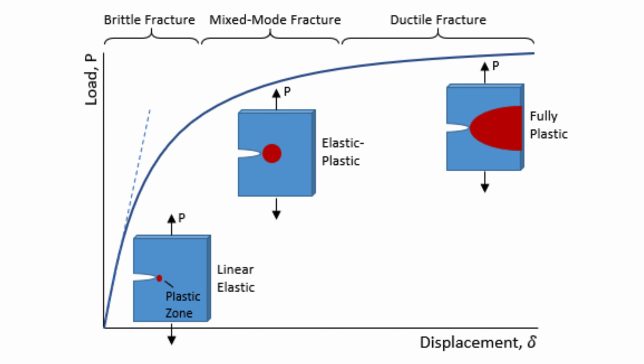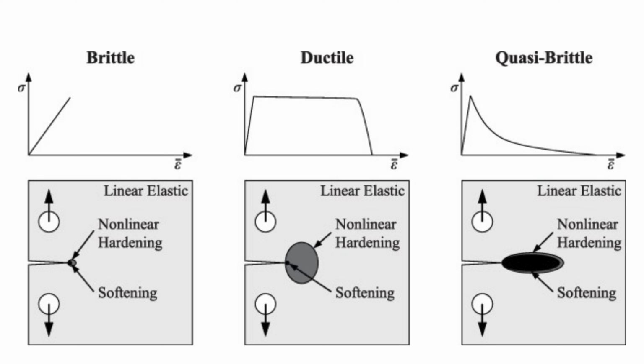In the immediate neighborhood of the crack front, a prefracture region is formed where weakening and rupturing of cohesive bonds occur. These processes occurring on atomic scale are beyond the scope of continuum mechanics. The prefracture region is usually enclosed by a zone of plastically deformed material. The deformations in this zone govern, to a great extent, the processes of prefracture and define the modes of fracture of a body. Depending on the size of the plastic zone, brittle, quasi-brittle, and ductile fractures are differentiated.